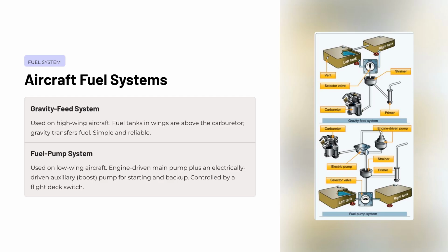You should always consult your aircraft's pilot operating handbook for the specific procedures regarding when to use the boost pump, as requirements vary by aircraft model. Understanding which system your aircraft uses is a fundamental part of pre-flight planning and safe fuel management.